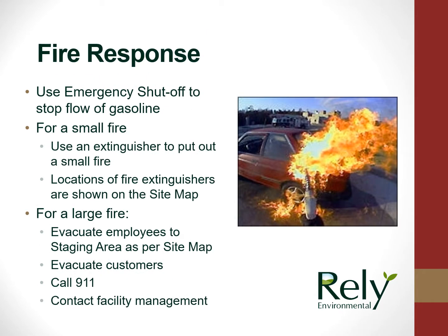In the event of a fire, use the emergency shutoff in order to stop the flow of gasoline. For a small fire, use an extinguisher to put out the small fire. Locations of the fire extinguishers are shown on the site map. For a large fire, evacuate all employees to the staging area as per the site map. Evacuate customers, call 911, and contact your facility's management.